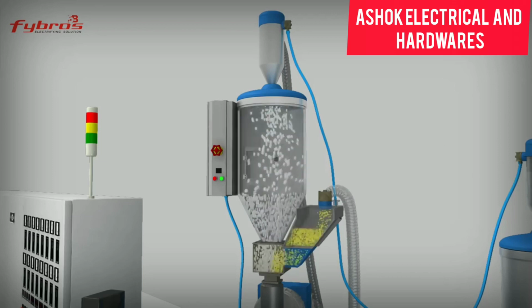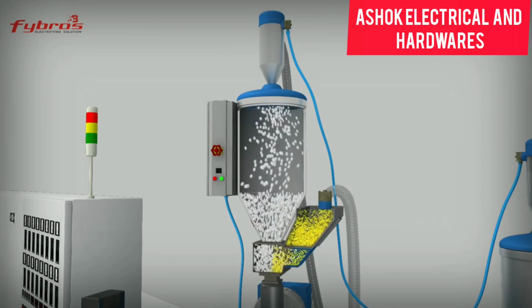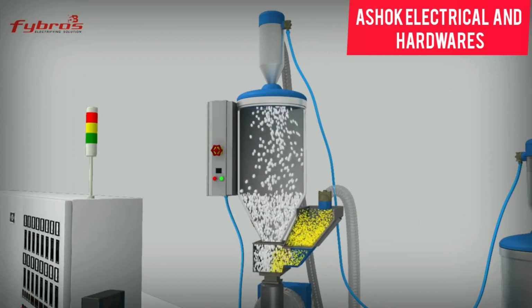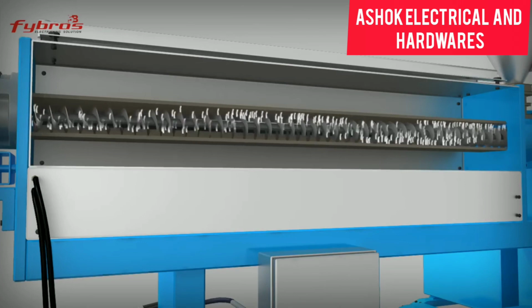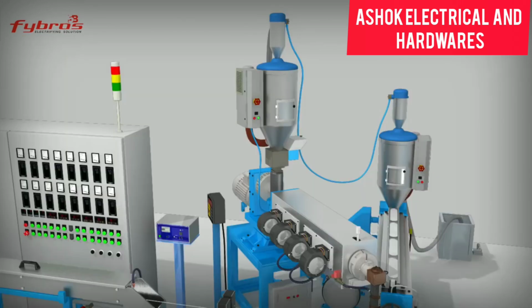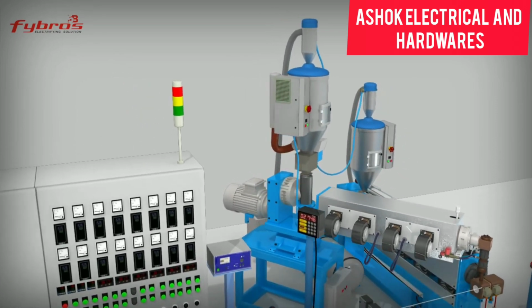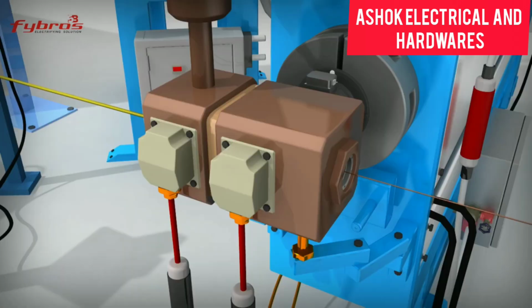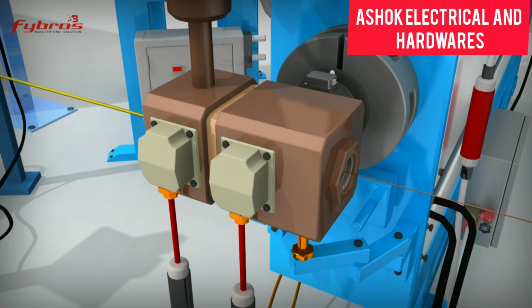In the feeding section, the solid PVC granules are fed into the extruder through a hopper. Then, PVC compound is transported along the barrel by means of a rotating screw. The barrel wall is equipped with a number of electric heaters which melt the PVC. This material is then pushed towards the die where the extruded final product is shaped and expelled.